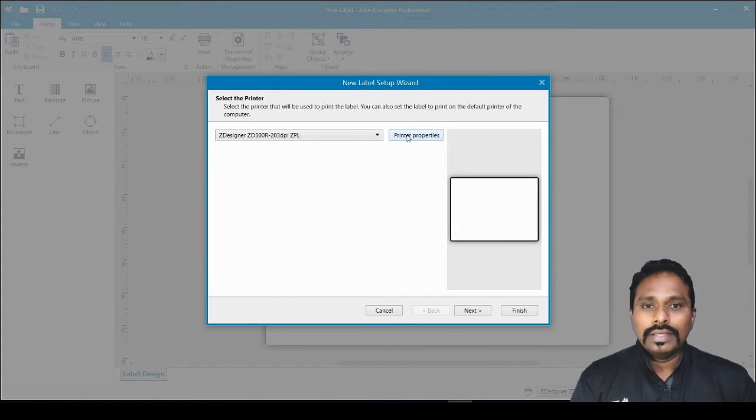You can do that, so you don't have to fiddle around with the Windows driver settings per se. Each label can have its own driver settings. If you want to change any quality parameter, the print related settings, you have to come back to the design template, open the design, and change its driver settings, not the Windows driver settings. If you change the Windows driver settings, nothing will take effect when you print.